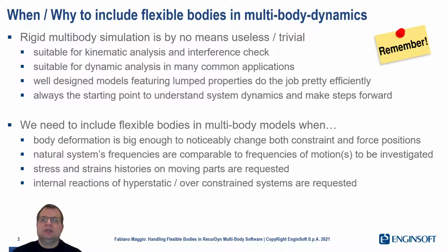As said, rigid multi-body simulation is the starting point in multi-body. And this approach is by no means useless or trivial. We still use rigid multi-body very frequently, and it's the best possible approach in terms of efficiency and calculation time. So whenever you have to perform just kinematic analysis or interference check, whenever your dynamics is slow and you don't expect to have large deformations of your bodies,